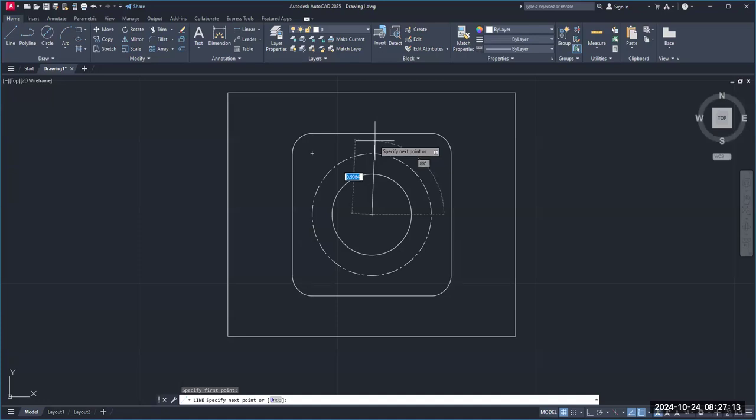So what I want you to do right now is hit the F8 button. Okay, and hit enter. Now, watch. That line disappeared, but watch when we draw the line again. Look what happens. It either moves perfectly vertically or perfectly horizontal. There's no angular. You can change the angle. And I'm going to click right about right there. Enter. I just drew a line straight up.